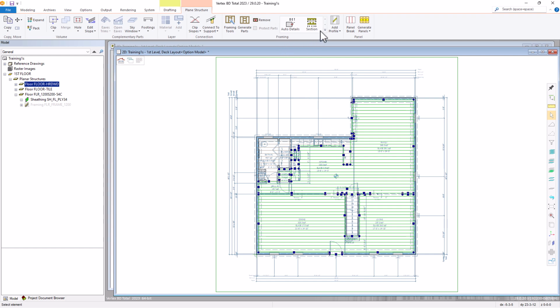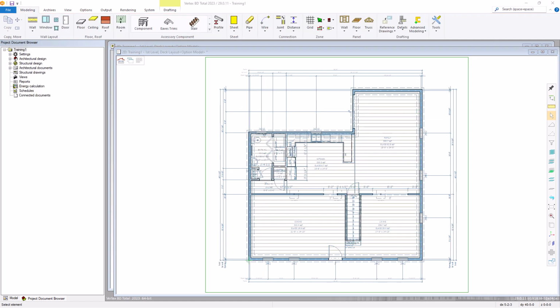When you look at the framing menu, the field and edge tools are not available, indicating that you did not select the floor framing layer. If you select the wrong layer, continue selecting layers until you pick the correct one. Hit Escape to cancel that selection.